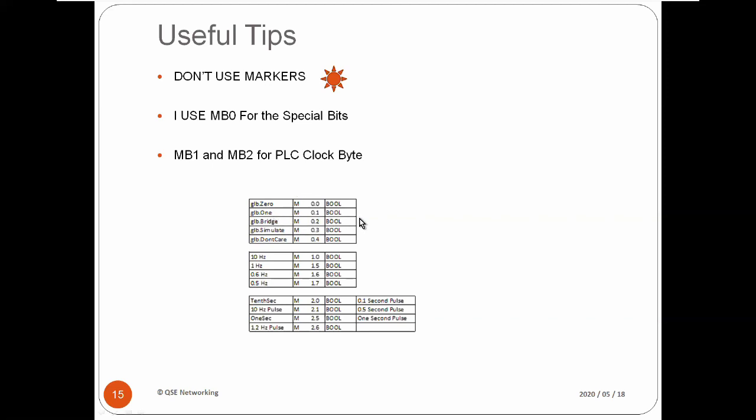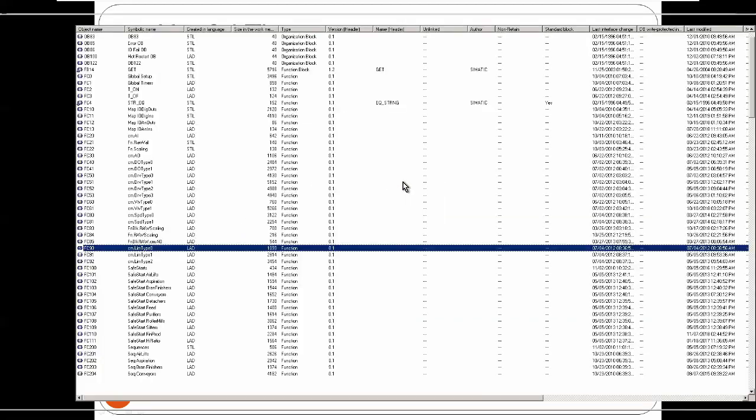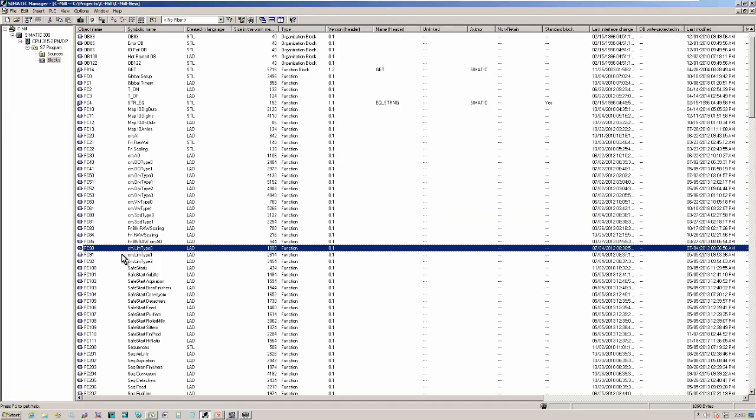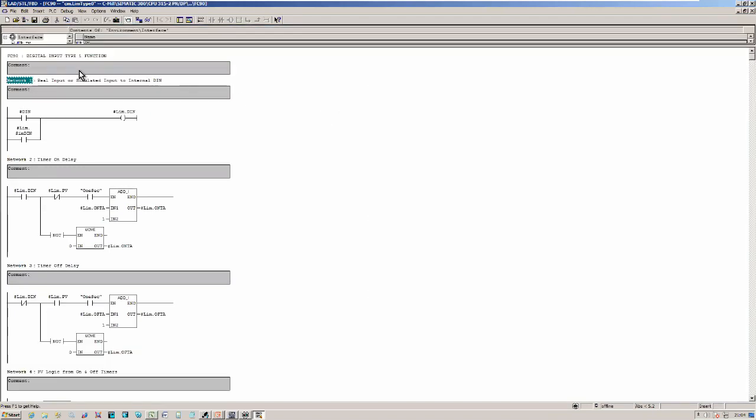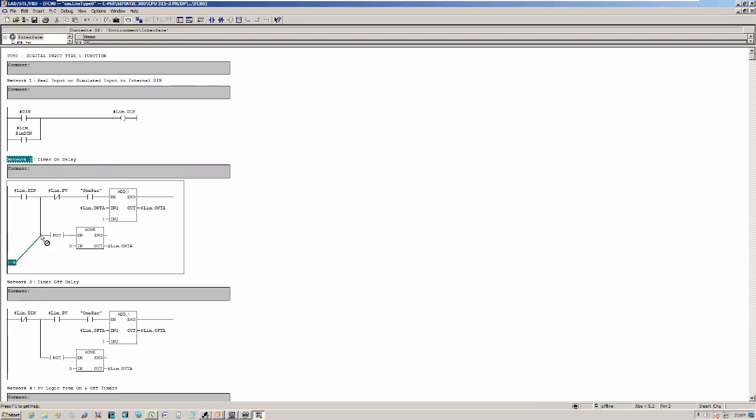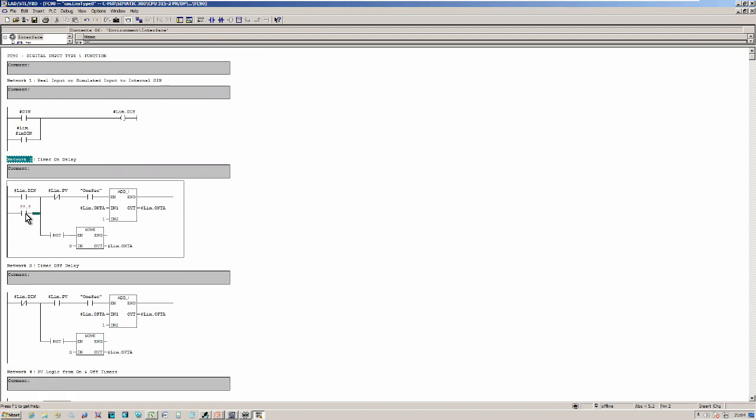This global bridge is a very important feature which I've always used. You know what happens? Let me go to our PLC program. Say some clever guy comes into my PLC program here and says, this is not working, so I'm going to bridge it. I do a bridge here. Oh, my bridge is not working. I connect it to there. No, this one doesn't work. Fortunately, I can put something else there and bridge it. In fact, I use a normally closed contact of the same thing.